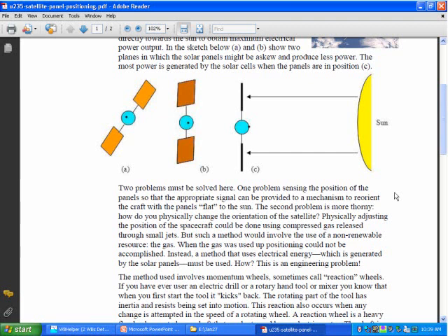Well, it turns out what actually is used in the industry in doing this is called a momentum wheel or a reaction wheel. And there are usually 3, maybe 4 of them in the satellite. Think about it this way. You have 3 different directions, right? Up and sideways and forward. So 3 axes of rotation hanging there in space.